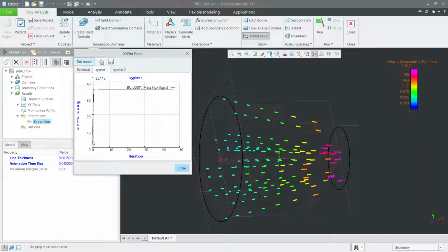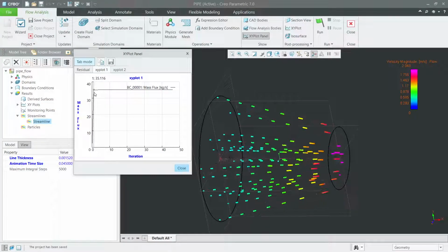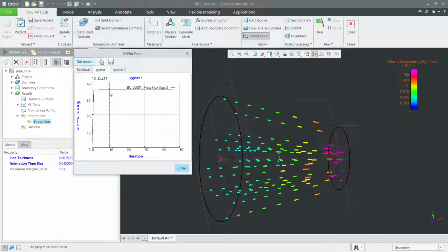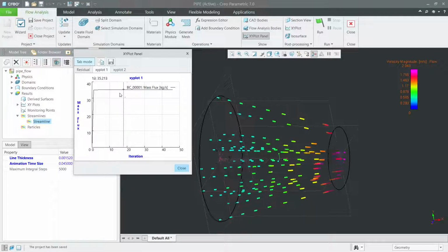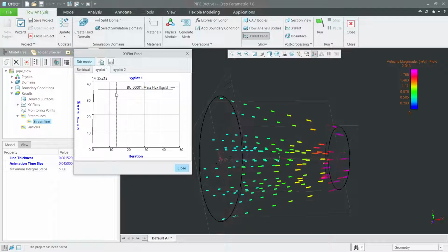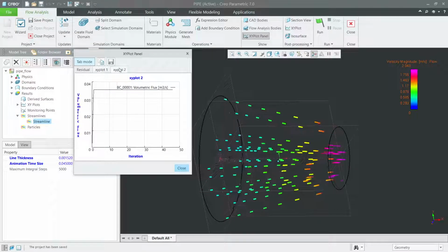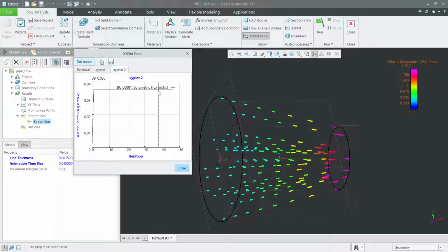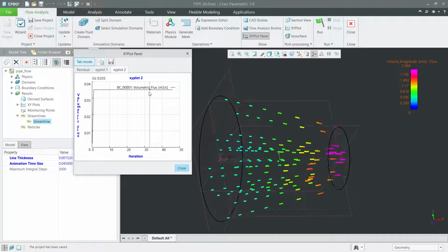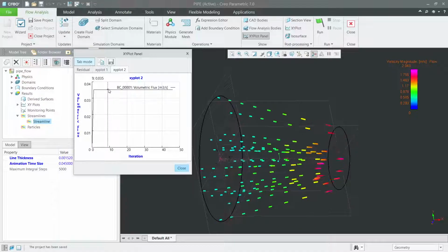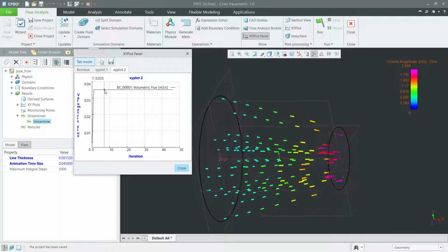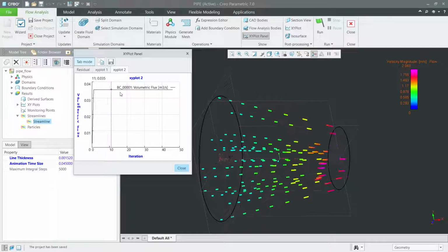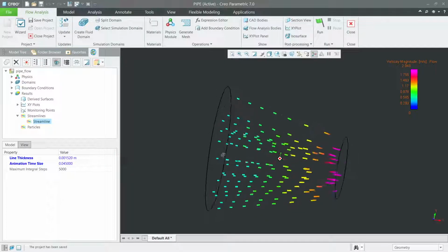You can see that at the initial stage the analysis is happening, and after some time the mass flow rate in kilogram per second is given, which is 35.212 kilogram per second. And in the second XY plot, which is the volumetric flux, the flow rate in meter cube per second, the discharge itself, is 0.035 meter cube per second, right? Click on OK.